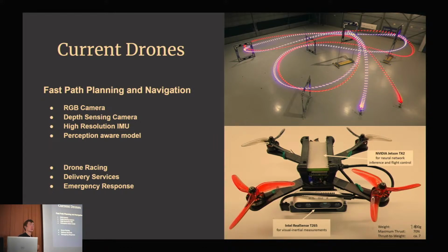We were receiving the data from, of course, the IMUs and barometers on board the flight controller. But moreover, they introduced an algorithm for detecting changes in the environment based on the camera preview. Basically, they took the 2D RGB camera video feed and ran an algorithm to make detections from movements of the camera. And based on that, they were able to track the 3D movement of the whole drone.